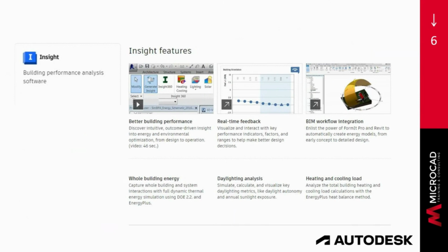It runs completely integrated with Revit, and you can run multiple analyses in Revit of the same project and continue improving. It will tell you your whole building energy and how you can run energy simulations and see how your building is doing energetically and in terms of how much it's going to need.